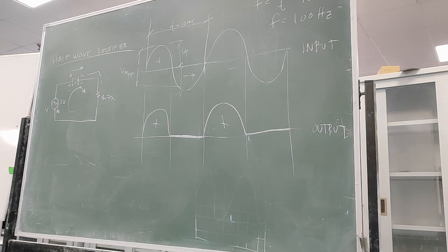Take note, we know that a DMM always measures in RMS. Remember that. In RMS value, right? In VRMS value. Therefore, the one that you will find here later will be a different number compared to the V peak-to-peak value. You get the idea? Alright?